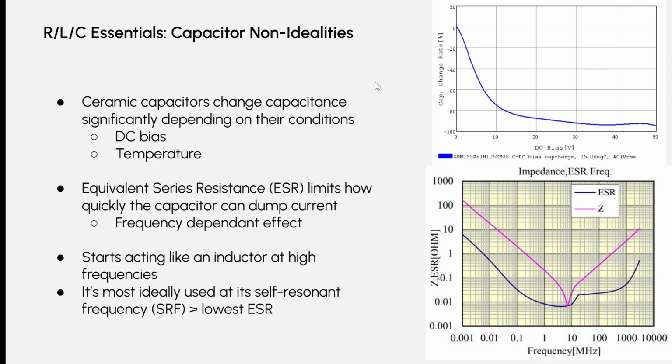So there are also temperature effects, which we'll cover on the next slide. But again, if it gets too hot or too cold, the capacitance value can go down like crazy. When you're designing power electronics, you get a capacitor rated for 50 volts. It will not explode if you give it 50 volts, but it will virtually suck. So you have to really consider that.